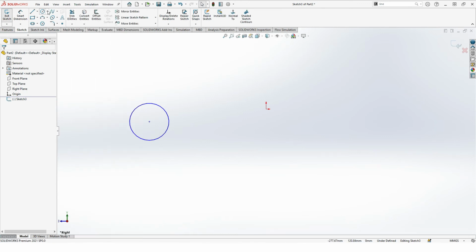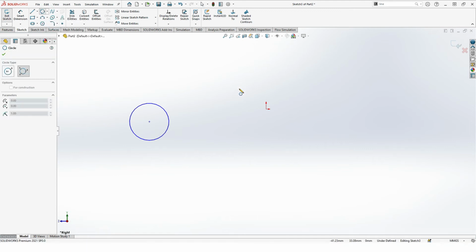Now the second is the perimeter circle. In the perimeter circle, just click the left button, one point is selected, and from the perimeter circle we can draw the circle. I have given the second point, and it is still asking what kind of circle you want, from here to here.